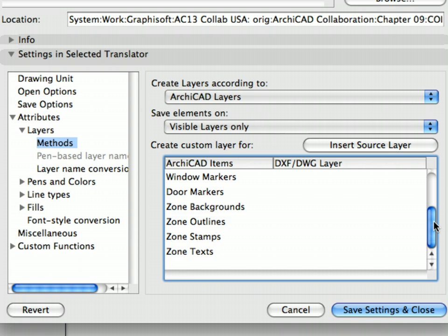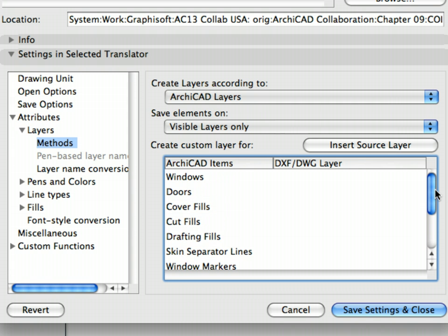In the resulting DWG file, we will export all ArchiCAD layers to a single layer. This was another request from the mechanical engineer who likes to have all the architectural data on a single layer so it can be easily displayed or hidden in his file.